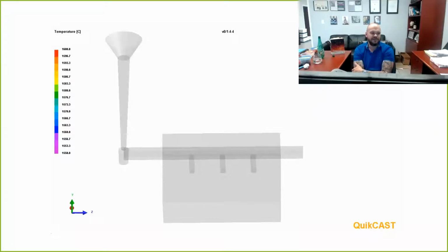We've got a sprue well, which the idea is it's going to cushion the metal from the fall. And I love the fact that we've even got calculations on what size the well should be. And then we've got a runner, right? And so the 1:4:4 means that at every opportunity for a metal transfer or transition from one feature to the other, we have an expansion of cross-section, right?